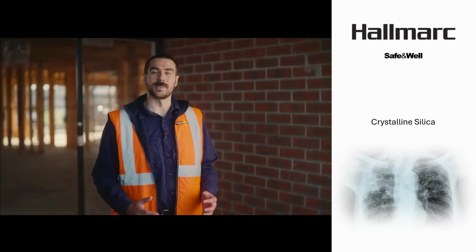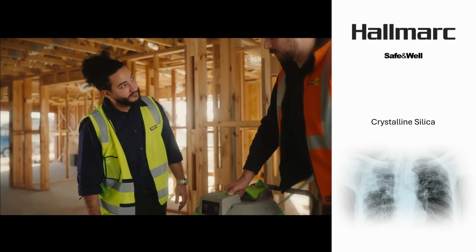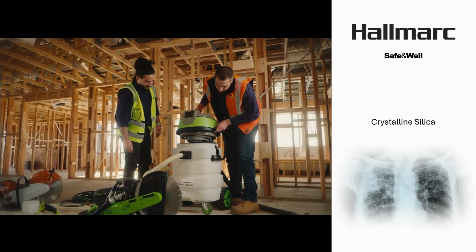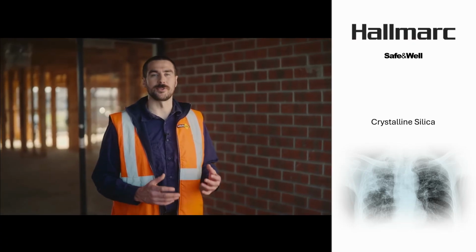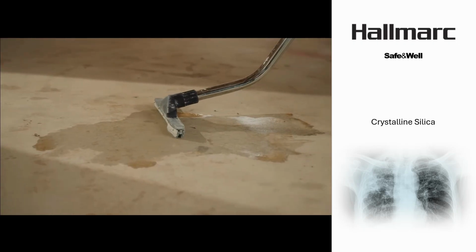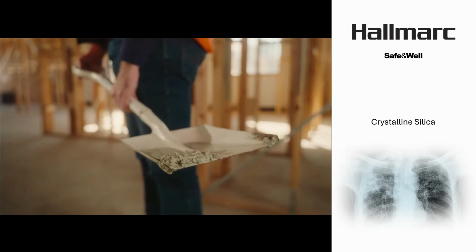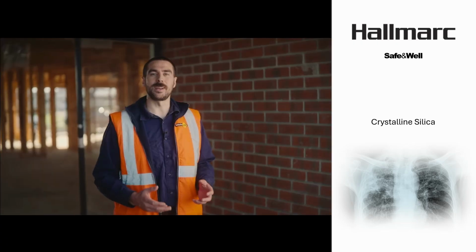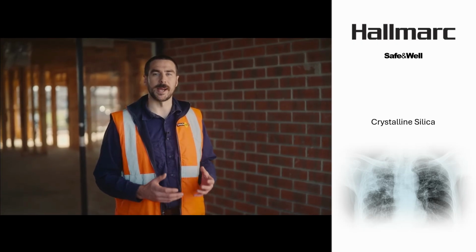On-tool dust suppression systems will create a slurry that contains crystalline silica. This is why it's so important to consider how and when slurry will be collected, cleaned, and disposed of, as re-exposure can occur if it's left out to dry. Collection and cleaning methods can include cleaning the slurry with a wet-dry vacuum, shovelling the slurry into a bag while it's still wet, or collecting the slurry at the source. Offcuts also need to be collected and disposed of appropriately to eliminate any further dust from being created.